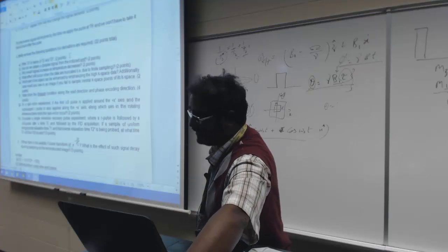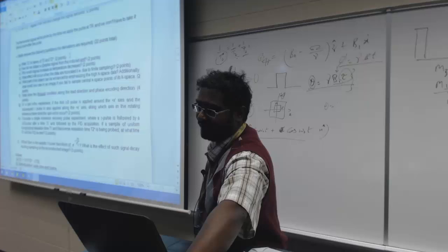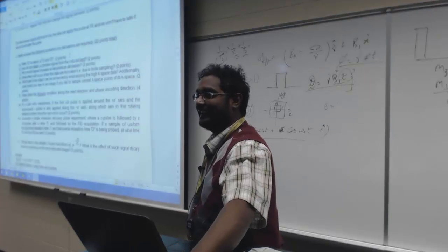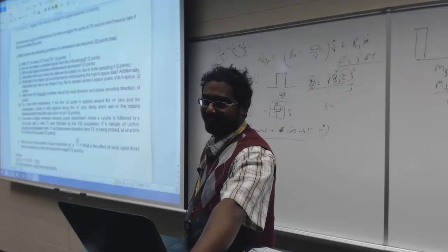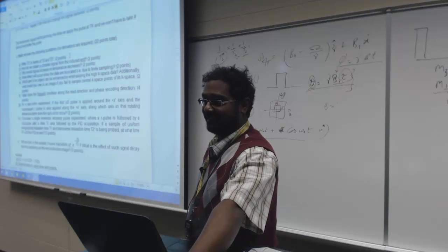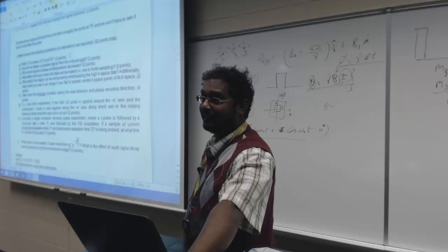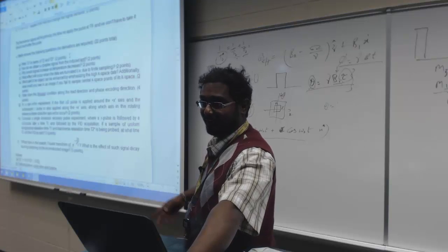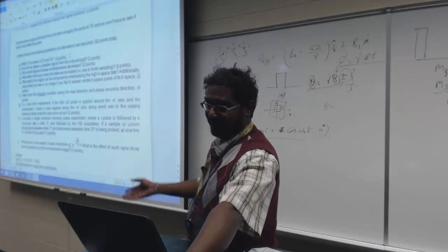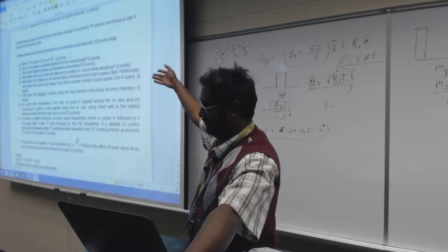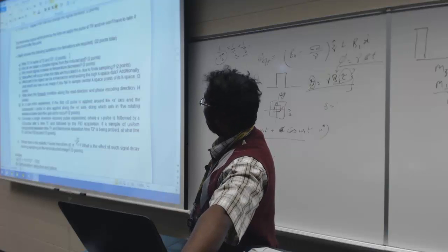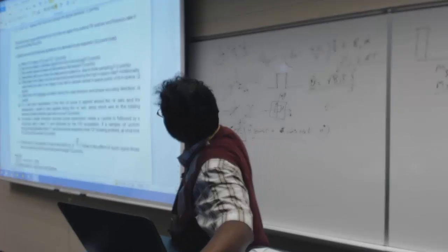So how do you obtain complex signal? I got a spectrum of answers on this. So does anybody realize now what the expected answer was? Demodulating the signal. I mean, we went through that, right? So you use the sine component and then the cos component to get the real and imaginary parts of it. So you get the complex signal.